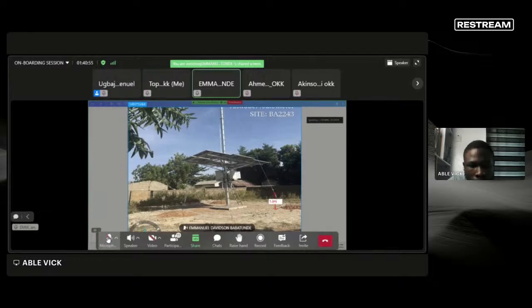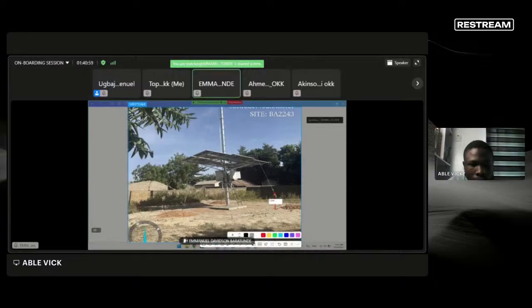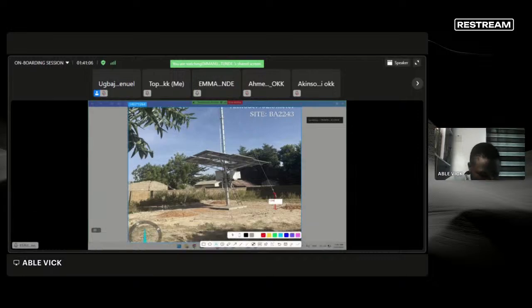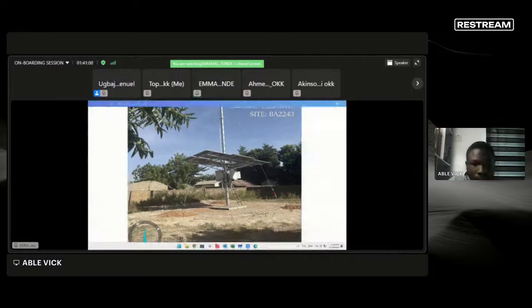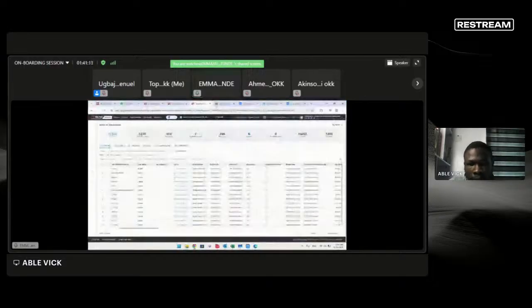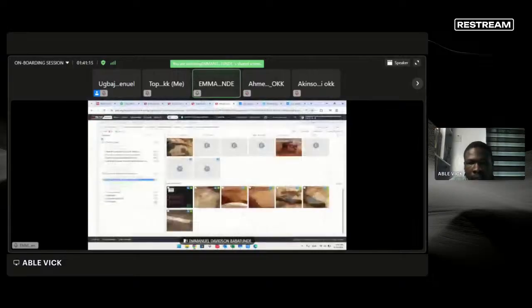Now you get your inclination angle of those guide wire to the tower. Then you backfill the trench. It's same backfilling in layers, and with your water. Then we know we're done with this.